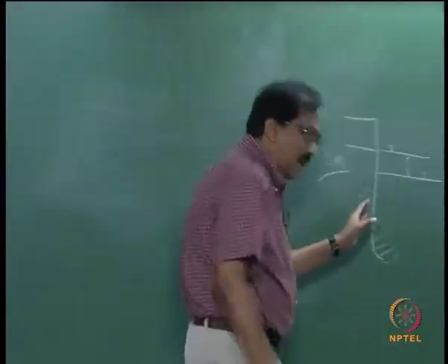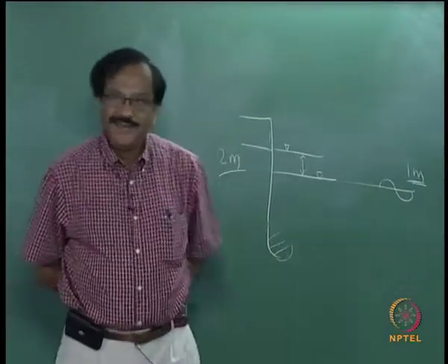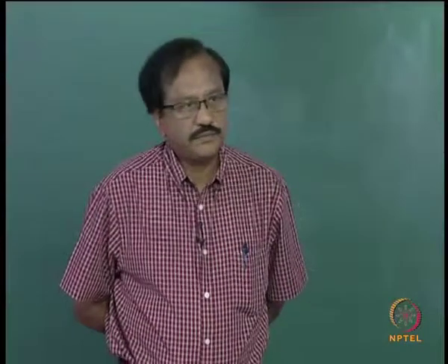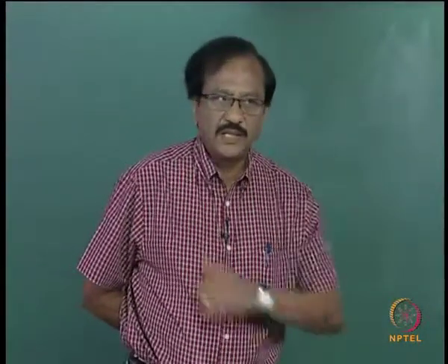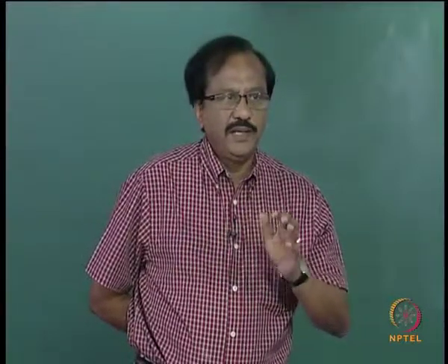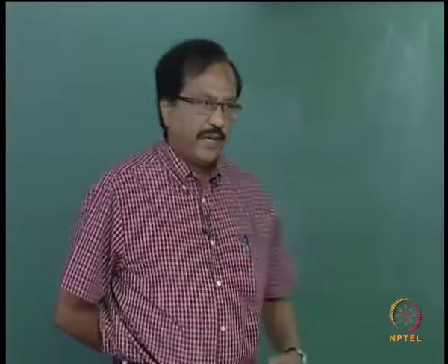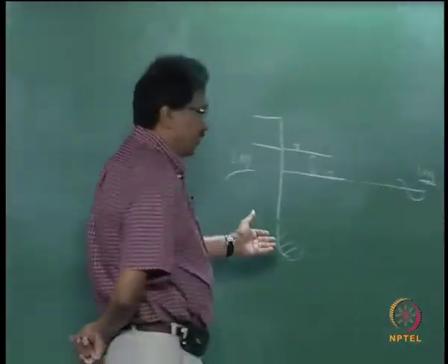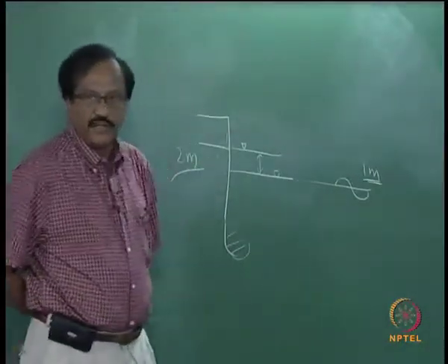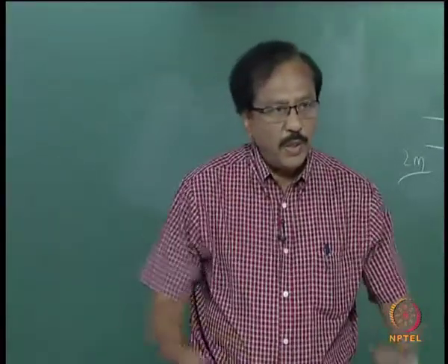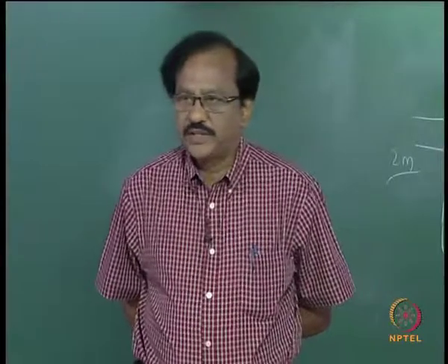So, vertical wall is not preferred when you talk in terms of coastal protection. For that matter, vertical wall structures are being discouraged, for the simple reason that the reflection is going to be high and the force exerted on the structure is high. But you cannot avoid vertical type of structures in general.